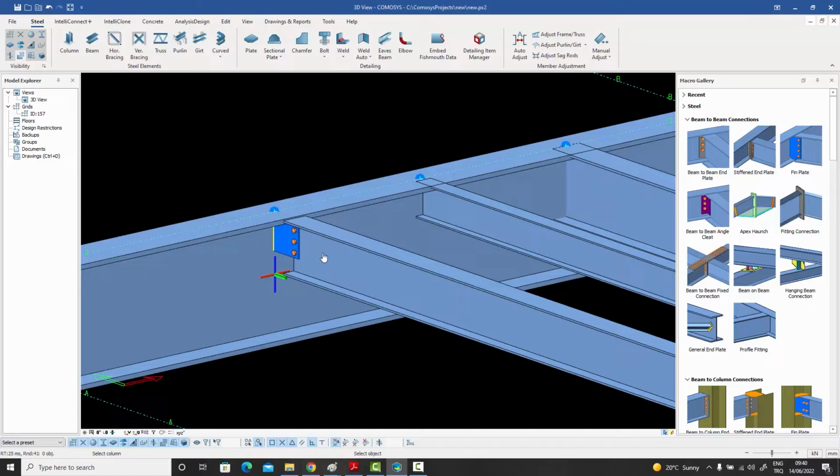By the way, let me also explain, because this is something I've been saying in other videos as well, why we need to right click 3 times. First of all, if this was a column, you could have selected the doubler plate over there, and then the fin plate would have been adjusted. Or you can select top stiffeners and bottom stiffeners, and since those are not here, that's why we have the right clicks.